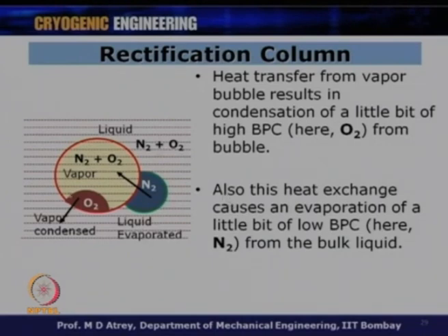So, the success of this column, or the efficiency of this column, basically depends on the efficient heat transfer between this vapor and the liquid, and therefore the design of each plate is very, very critical. The design of the hole at the bottom of the plate, which decides the bubble size, is also going to be very, very critical.